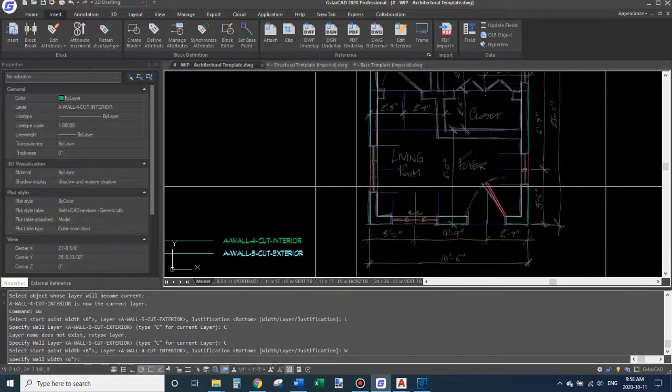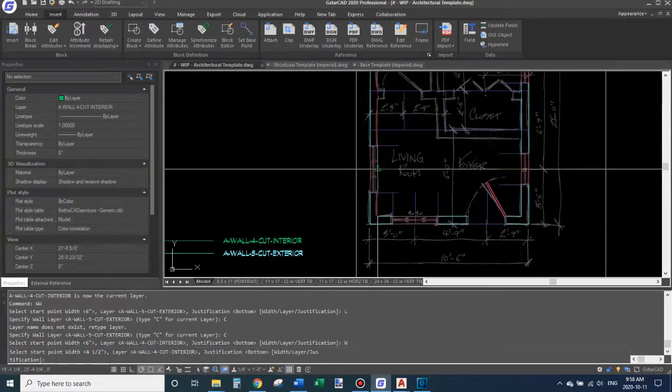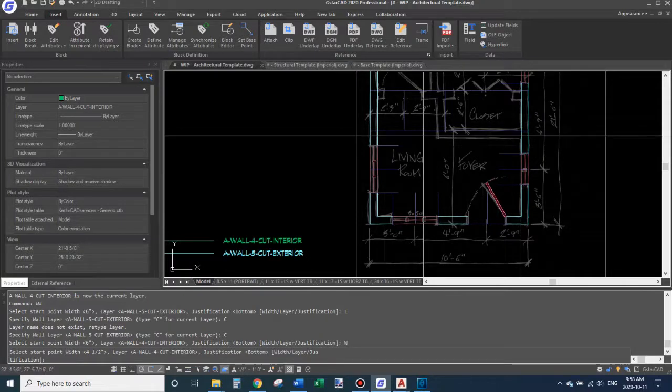Oops, I got to change the width. I'm going to change the width to 4.5. Using 6 as the exterior walls, it's kind of arbitrary, but the exterior framing will most likely be 5.5 inch wide studs, 1/2 inch gypsum on the inside. There'll be some poly, but you can say that's 0 thickness. Then exterior sheathing would be probably thicker than a 1/2 inch, probably 5/8 to 3/4 of an inch. So 6 inches, that's maybe not a realistic wall width.